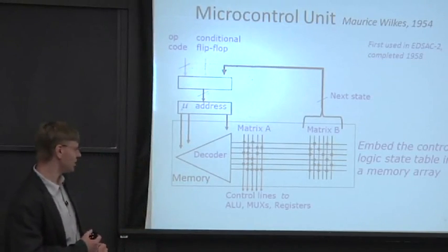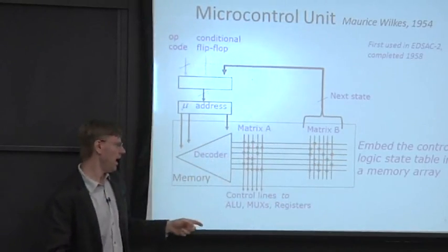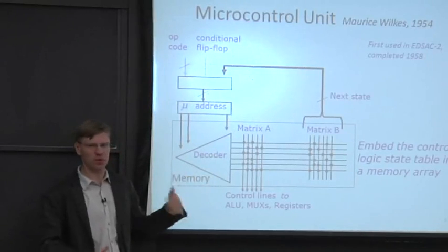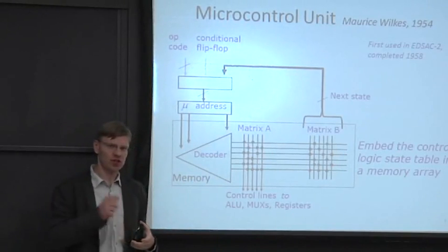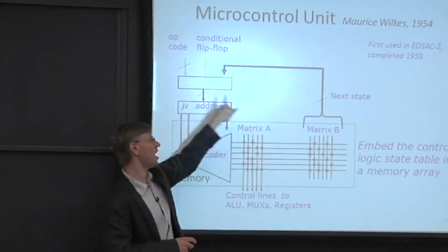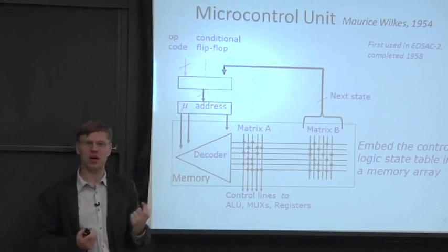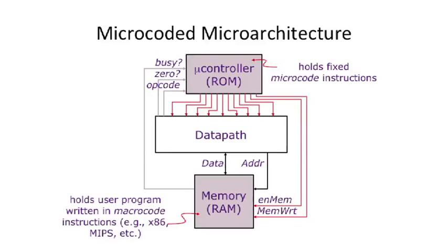Last thing I wanted to get across here is this is typically a ROM, and you can actually cycle through it multiple times, and the ROM is going to tell you where the next micro-coded instruction is. So you'll be basically cycling around this loop multiple times, or maybe only one time, depending on the actual instruction you're trying to execute.